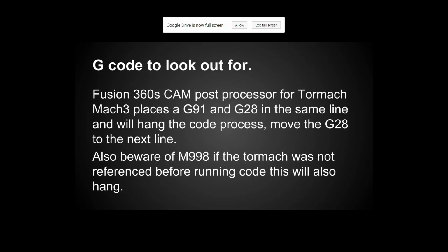It is a semi-automatic tool change. You have to open the motor case, put in the tool, re-zero the height. There's not an automatic tool height setter. There's not tool height compensation or tool diameter compensation on the machine automatically. So you have to enter in every tool height manually on the machine, or use a paper trick with cigarette paper or a Post-it note to gauge tool height off the top of your stock. That is a time-consuming process. If you have 47 tools, if you're doing it manually, you're going to add at least 30 minutes to your machining time before you even start.